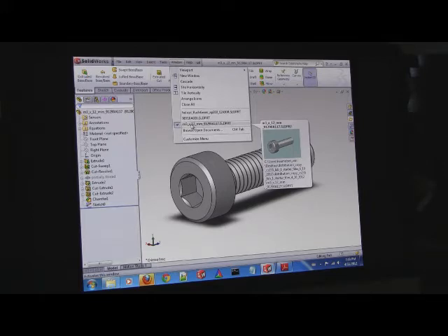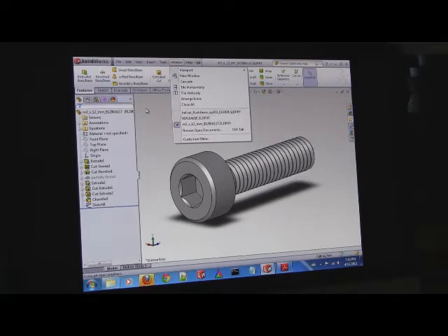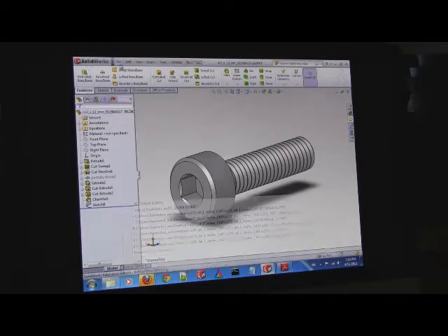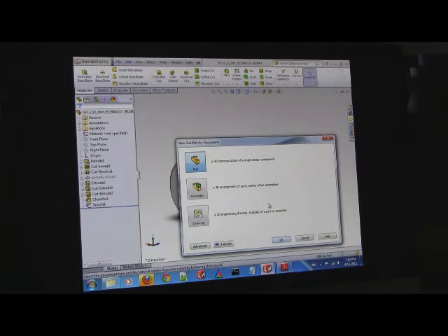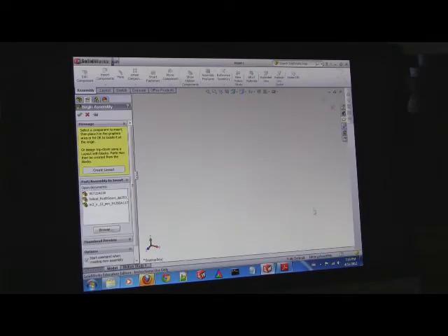Okay, everybody got the screw and the nut? Jonas, the first thing you need to do is download an M3 by 12 screw and a nut from the homework instructions. The only thing we've made in SolidWorks thus far is a part. Now we're going to make an assembly. Go to File, New, and on my screen it says Part, Assembly, Drawing. You're going to click Assembly and hit OK. Now you'll see a Begin Assembly thing. Just hit X there.